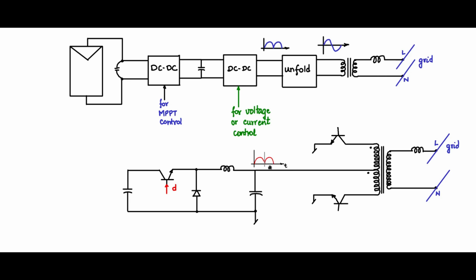Now we will unfold this. So what I will do, this is Q1. I will switch on Q1, which means during Q1, this is the operative half sinusoid, and the dots, observe the dots here, and I am supposed to get this. So when this is switched on, this dot is positive, so the positive comes in here.